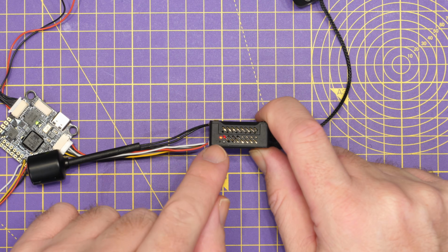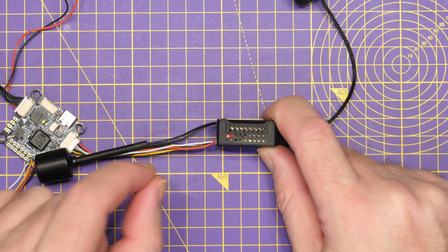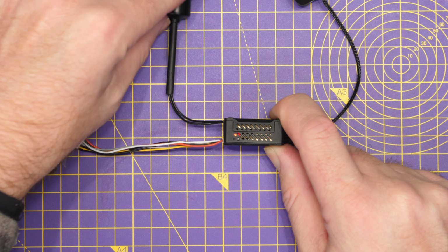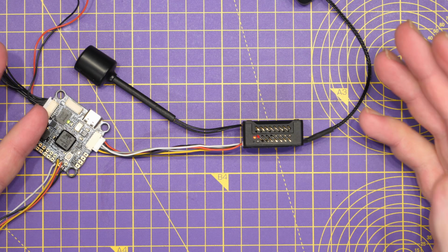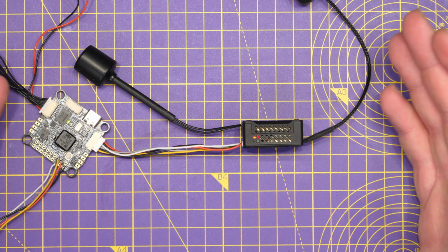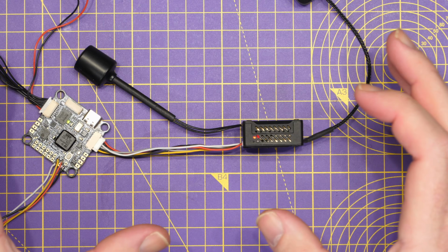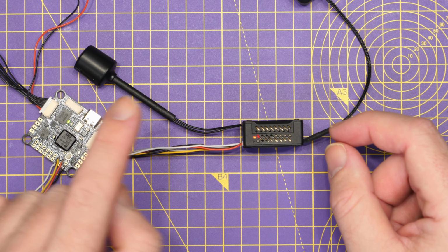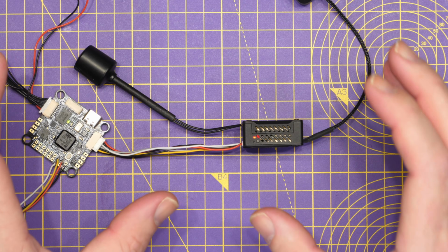If you are not getting that LED, your E unit is not receiving power. You should then look at how it is connected to either your power supply or your flight controller. For instance, if you're using an aircraft such as the Defender 25 from iFlight, that actually has a power switch on the VTX output that will not supply power to the E unit unless you've got that option properly configured.